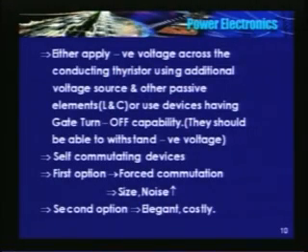This option is a bit elegant compared to using an external circuitry to turn off the conducting thyristor. This is elegant and maybe a bit expensive. The first one, since I have to use an auxiliary circuit, my size increases, cost increases, and it is noisy. So the present day trend is to use the second option, using the self-commutating devices.